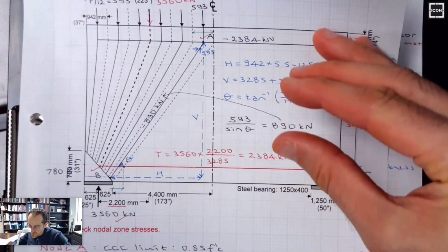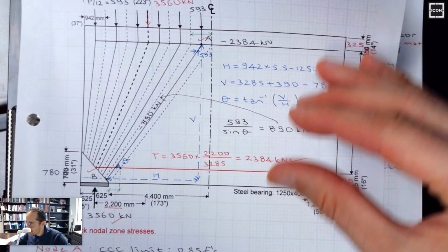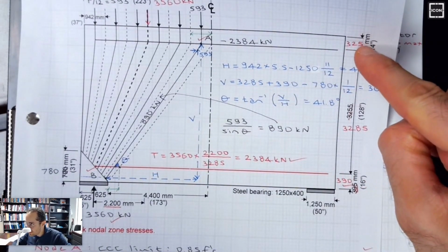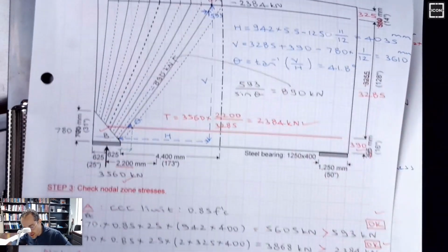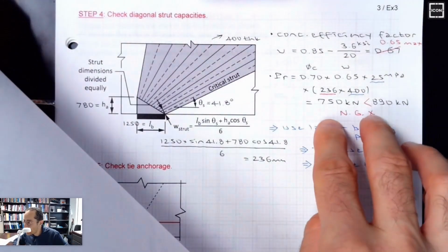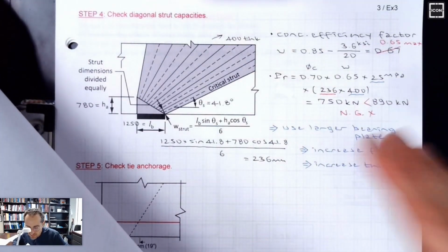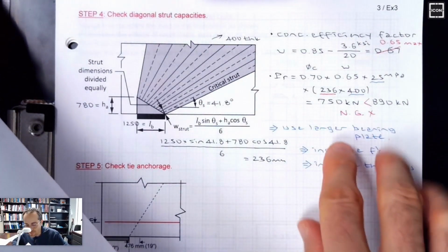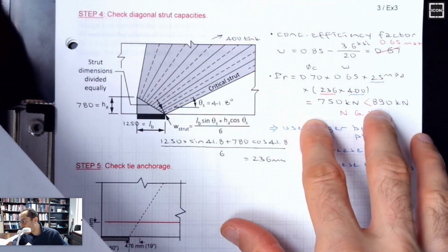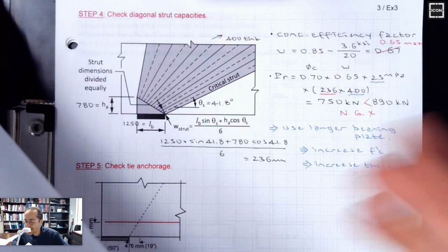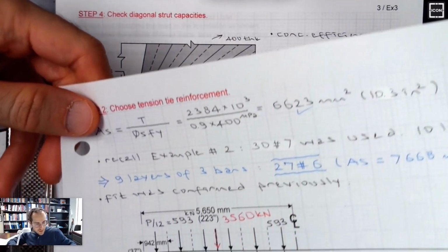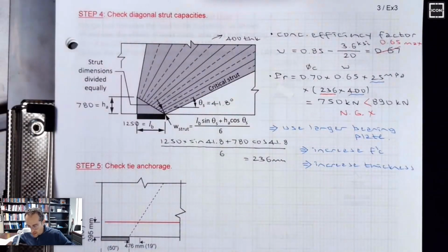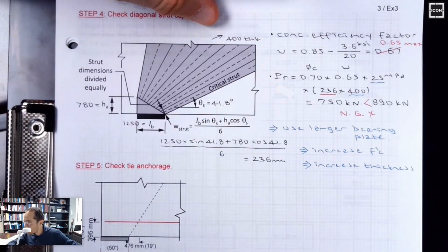That's going to be, maybe shift the model a little bit above, maybe 25 millimeter above from both ends. This becomes 300, this becomes maybe 425-ish, and see how it works. So if it's an existing structure, you have some calculation to do. The overload is not huge. If you see a major 50%, 60% overload, it's not a good approach. I don't think it would fail, but in this situation, maybe 18% overload, maybe you'll reduce it to 4-5%, and it's an existing structure. You might say that 4% overload is acceptable, and you might pass it for that situation. So, but I would proceed. I'm not going to fix it.